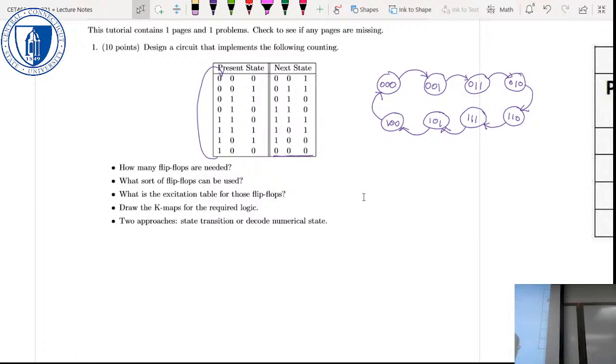So then all that I have to do to get that is to write down my state information, 000, 001, 010, 011, the standard counting from 0 to 7. And then these are now outputs. Right? So when I'm in state 0, I need to give that. When I'm in state 1, I need to give that. When I'm in state 2, I need to give that.